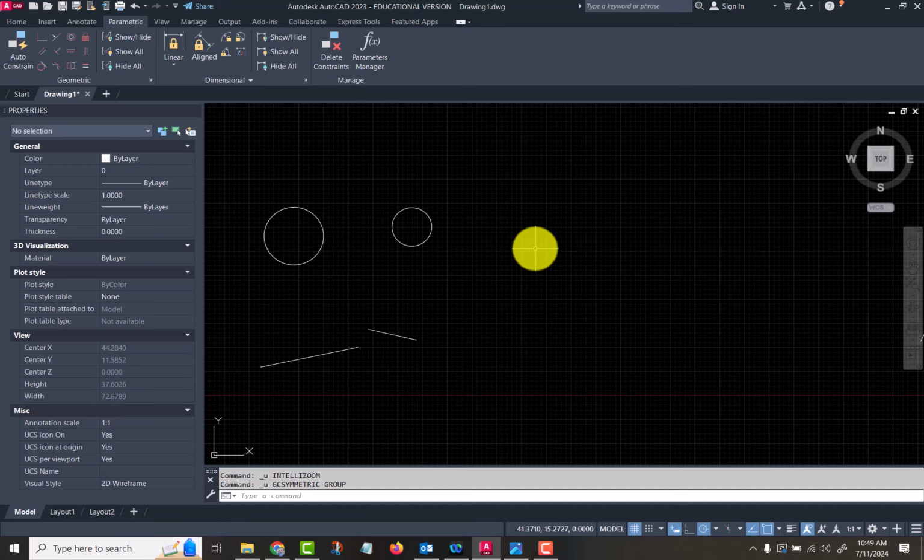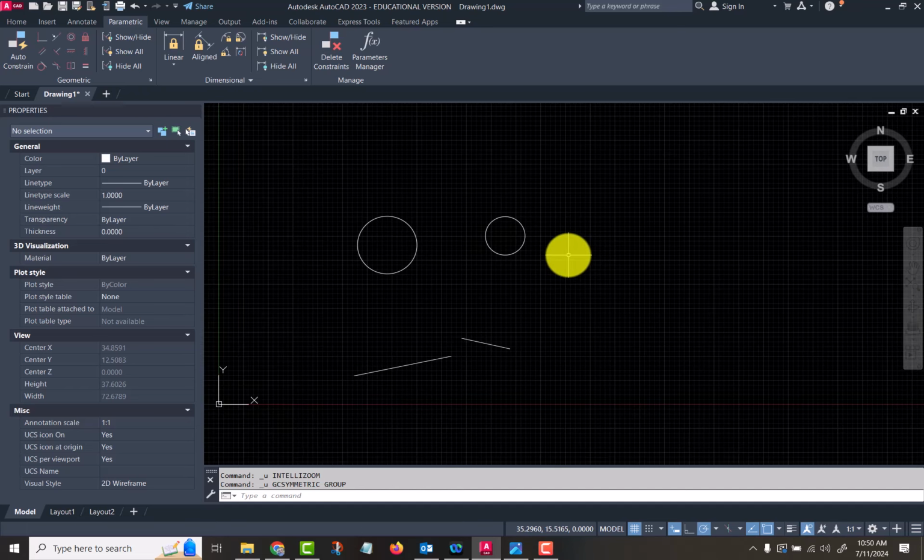And so AutoCAD has the ability to do constraints. It's a little cumbersome. It's not as easy and as streamlined as it is in Inventor, but it will work. So open up just a new file and just kind of play along with me. I'm going to describe and demonstrate the geometric constraints. And so on your menu bar up here, you go to the parametric tab, and over here you've got the geometric constraints, which is what we're going to work with today.